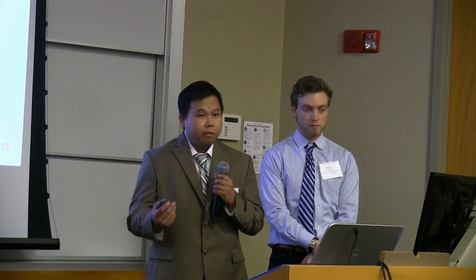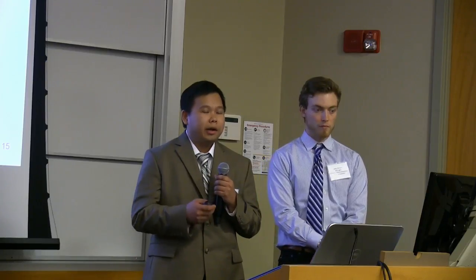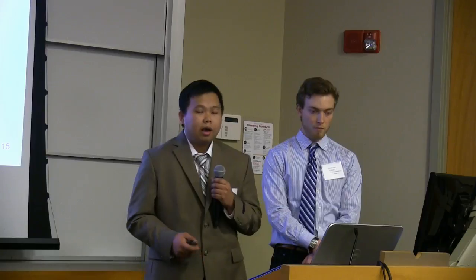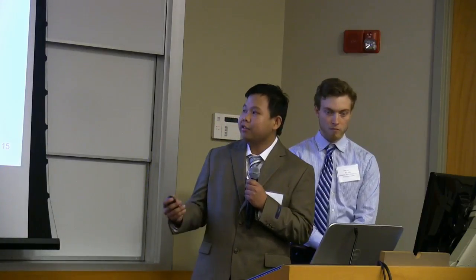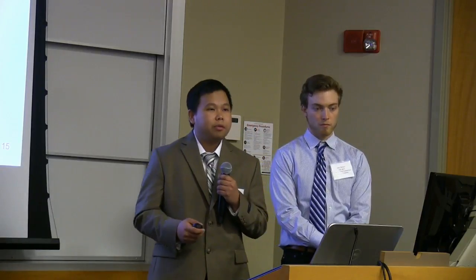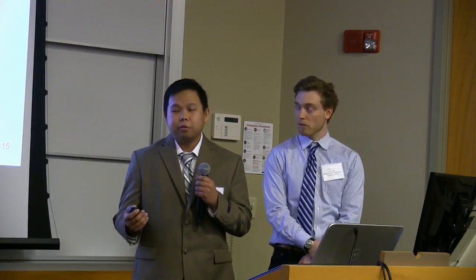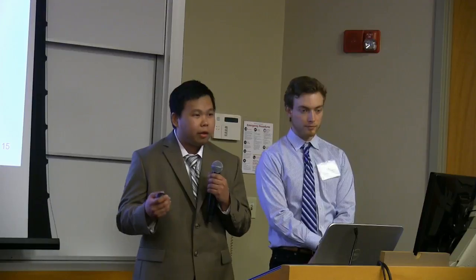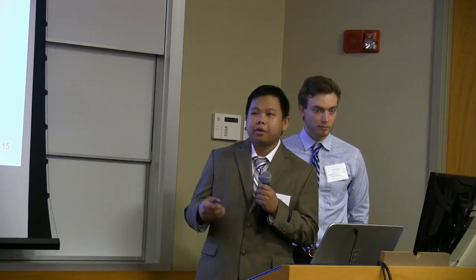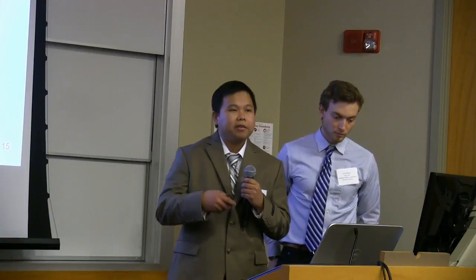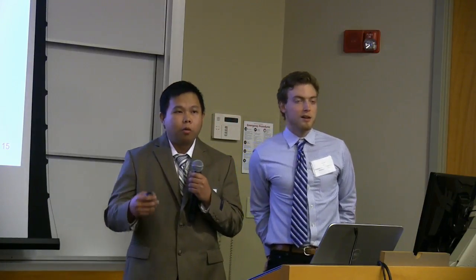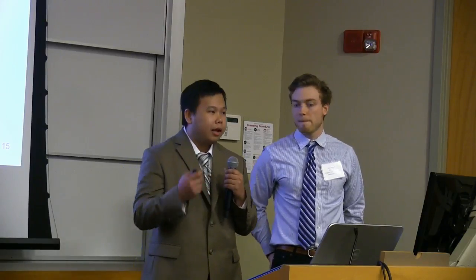We designed our turbine to have a rated wind speed of 11 meters per second. However, for the control, we designed it to start regulating the speed at around 6 to 7 meters per second. This is to ensure that a sufficient amount of current is commanded to charge the storage element when the turbine is experiencing wind speeds between 6 meters per second all the way to the rated wind speed of 11 meters per second.